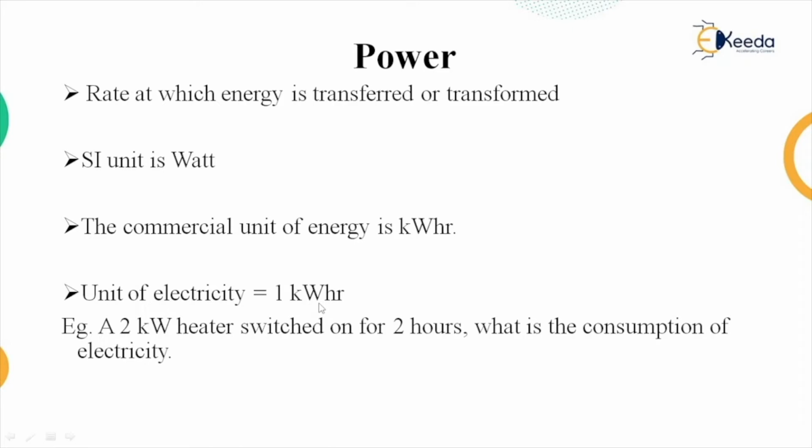For example, a 2 kilowatt heater is switched on for 2 hours. What is the consumption of electricity? We have to calculate the consumption of electricity in units. The given is a 2 kilowatt heater for 2 hours, and 1 unit is equal to 1 kilowatt hour.